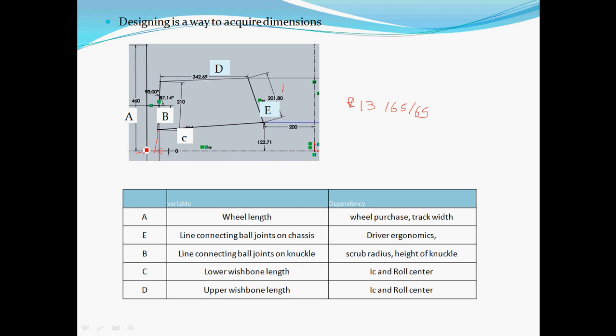The next thing is that, see, inside the rim you have space. Now you should not utilize the whole space. What I mean is that you should consider serviceability also. Like if you're designing a knuckle, and it's too big, almost touching the rim, then it will be very difficult for you to change camber and do everything. So you should have some gap between the rim and the knuckle, such that you will feel comfortable operating with it. Okay, so consider that also.